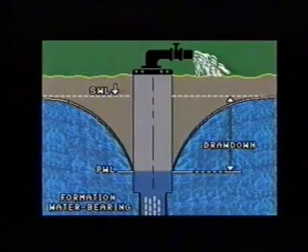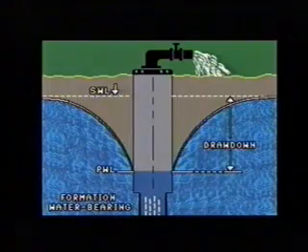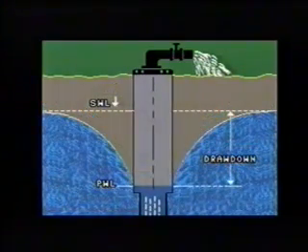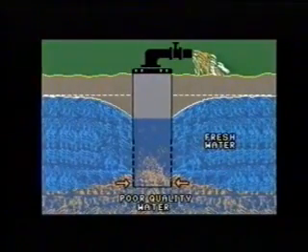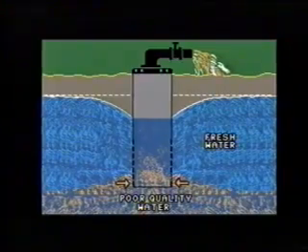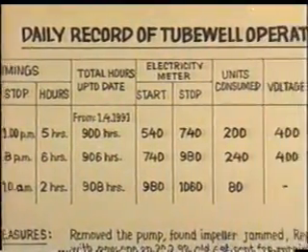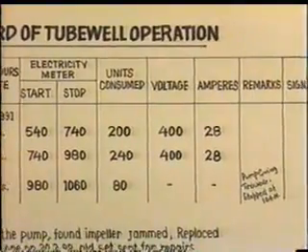Well failure may also be due to causes like decline in water level, clogging of screen due to incrustation and corrosion, rupture of well assembly, rushing of sand, and deterioration in water quality. Hence, for better performance of a tube well, a routine maintenance program is very essential.